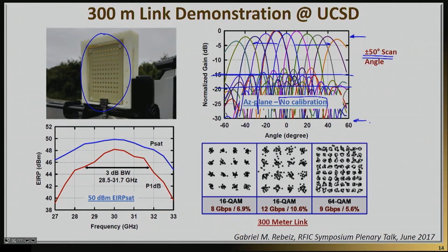But if you do the calibration, and in some applications you do need that, for example, in satellite comm, we often have to get the side lobe down to the 30 dB level because we can't radiate somebody with too much power, then you actually do need calibration and get this thing done. But in most applications, I would say a side lobe level on the order of 20 dB is more than acceptable. And that really shows the promise of having these things potentially work uncalibrated.